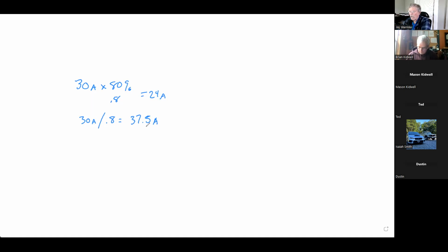There we are. 104. 106 is where the table for conduit fill is. Okay. So if we look at this, then yeah, we're going to need 8 gauge wire because it's 40 amps. So logically, it makes sense that if the capacity of the wire to carry amps is reduced, I should need a bigger wire.